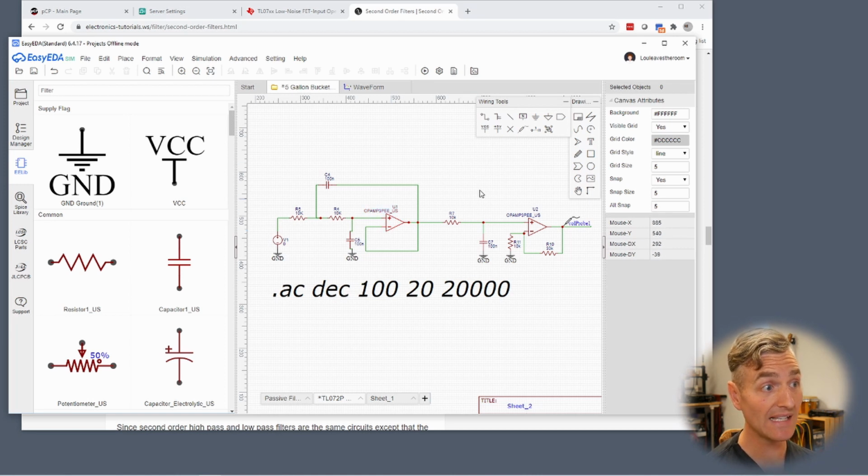And then we have a second entire stage, which is a second low pass filter, RC. Again, 10K, 100 nanofarad. Over here, we have a gain stage to overcome any of the losses that may have happened and just boost the signal. Who knows? Let's just see if that helps get our signal up out of the noise floor. And perhaps we can see more of that slope. We want to see a nice, steady slope.